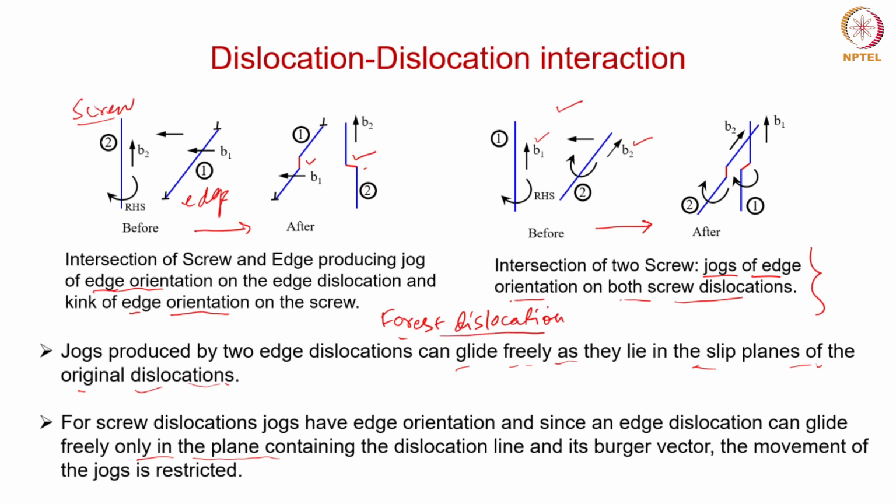This essentially means that the dislocation density is increased due to the cold working which is given to the material, and as a result, a lot of dislocations are present in the path of other moving dislocations, right? So this kind of dislocation is also known as forest dislocation.